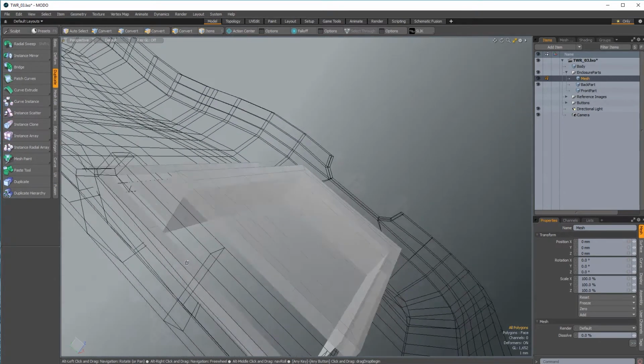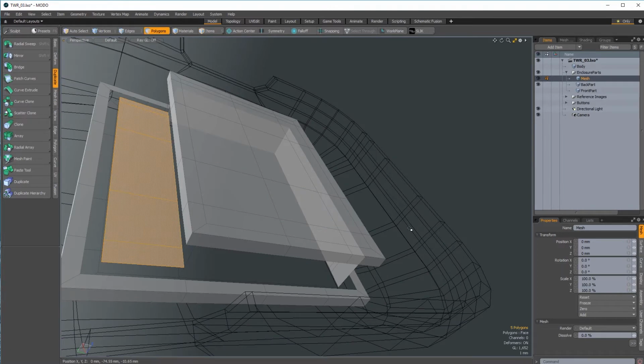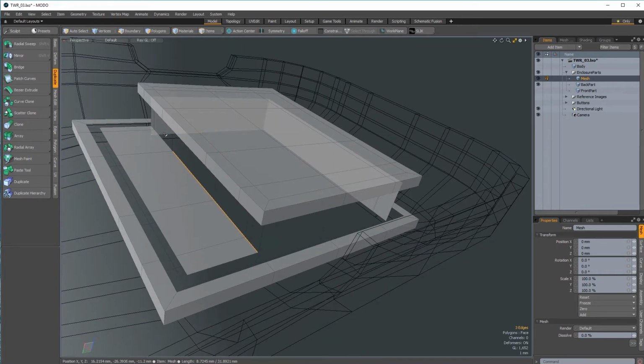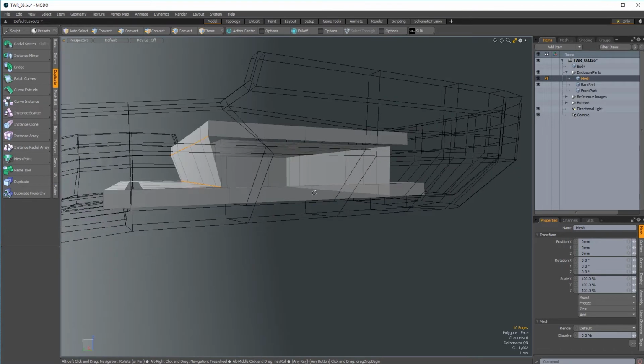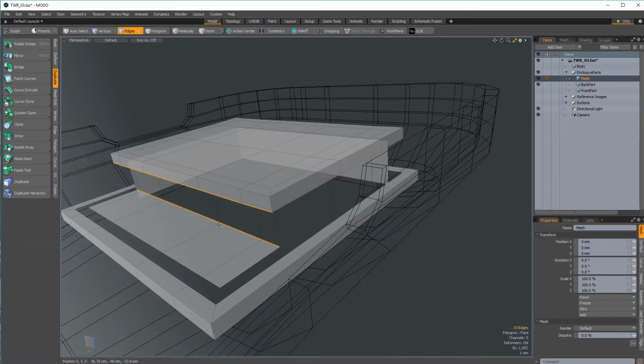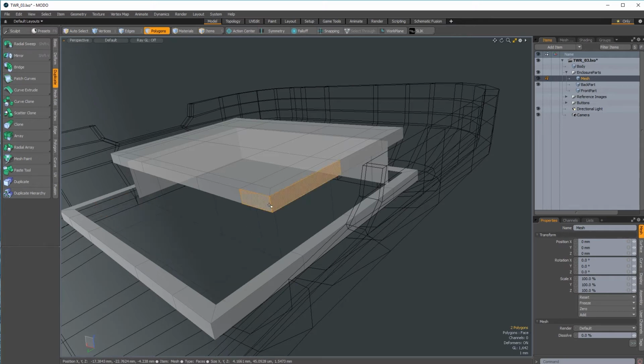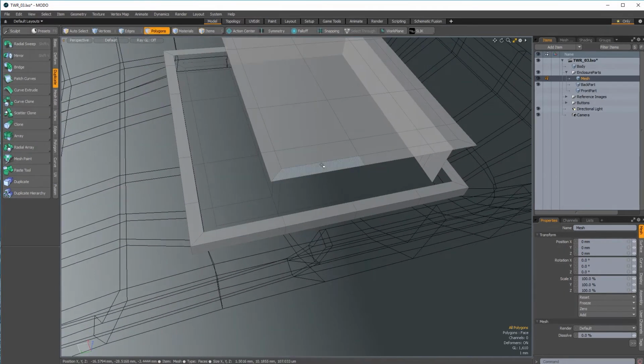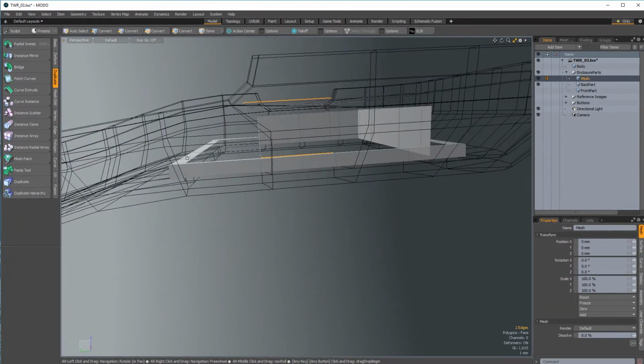And this set of polygons here is going to give us some problems. You can see that if we were to try to reconnect these edges with these edges, we'll give ourselves an undercut, which is definitely what we do not want. So I'm just going to delete them all together. We can put them back in later, and I'll delete this loop of polygons as well. Now, we need to connect this edge to this edge, but that will just give us an undercut as well.